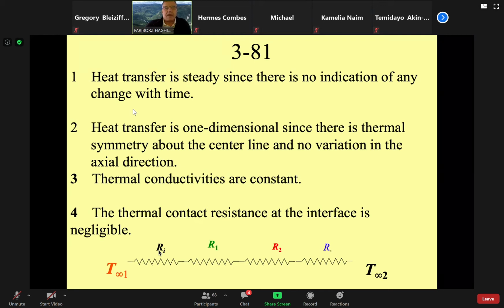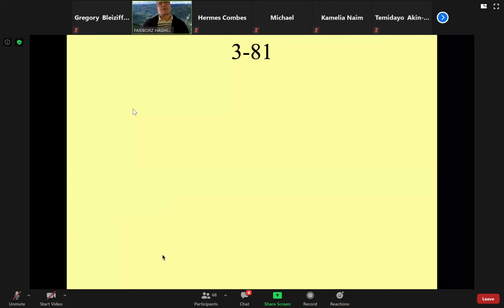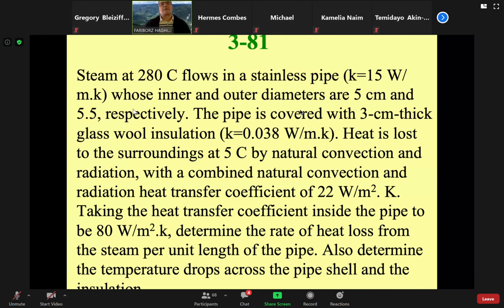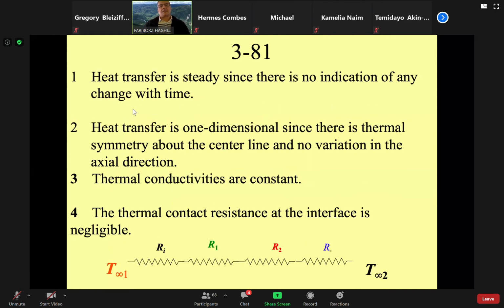Now let's go back. This is defined as 1. We are dealing with heat transfer from the fluid to the pipe. Therefore, the area for the transfer to the fluid is the interior surface of the pipe. The contact area is 2 pi R L times this. So that's here. Please do the rest.